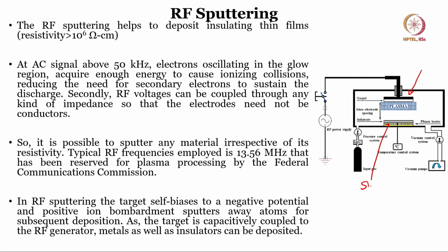So, this is a substrate on a plate, this is a target or source, and the reason for having this planar heater is to improve the crystalline property of the film while the atoms are depositing. It can rearrange itself.